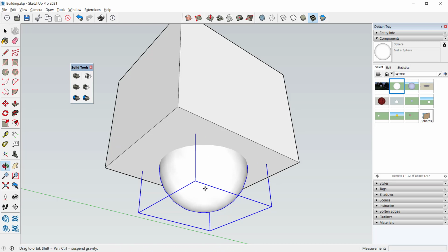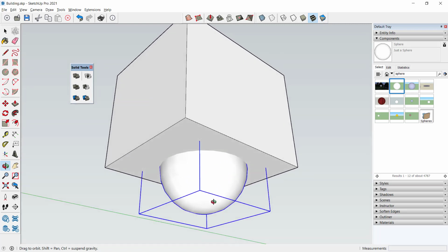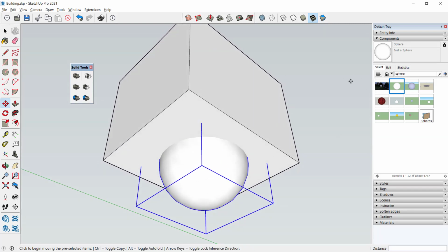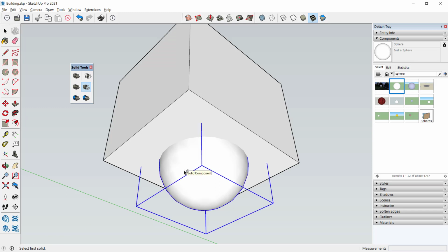groups. So for example, if I wanted to create a dome space, there are a number of ways I could do it, but the easiest way is I just downloaded a sphere, and I can use the subtract tool. Let me just deselect by clicking off of that sphere, click the subtract tool, and down at the bottom, and the cursor, it tells you to select the first object, which is the cutter, and then select the second object.